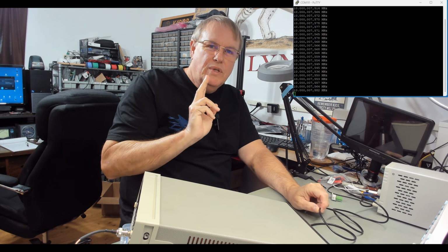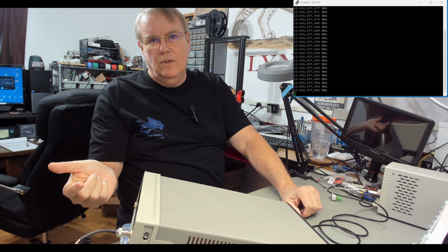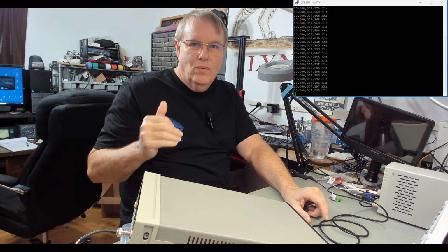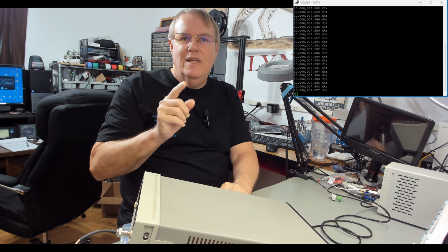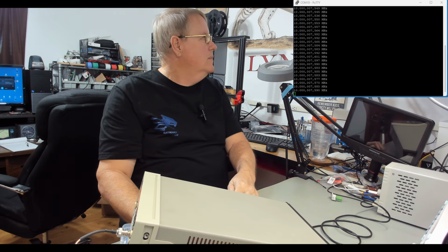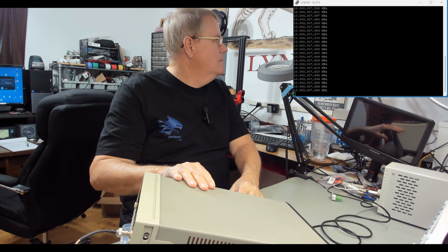If you want to use a USB from your computer to a COM cable for this print port, make sure you're using a normal one, not a null. And you saw the settings: 9600, 8, 1, none. And make sure that your DTR is set to high. That apparently causes it to stop running. It doesn't run; it waits for something. So apparently it's waiting for a DTR to go high from your terminal or your software. So with that, we got it working. COM port works fine.